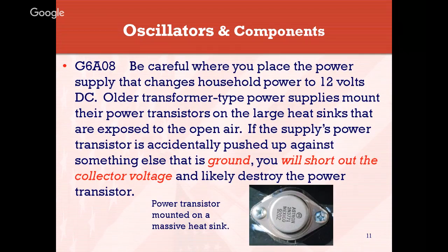You have to be careful where you place power supplies. The type of power supplies we're talking about are the ones that you plug into the wall and you get 12, 13, 14 volts out of it. Your older transformer type power supplies mount their transistors on large heat sinks that are exposed to open air.